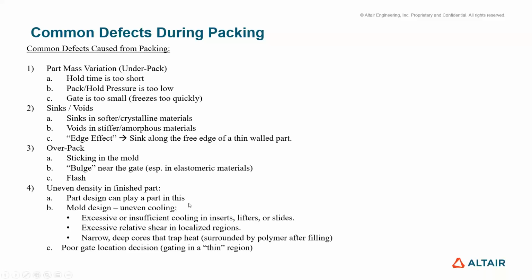If you're having dimensional problems, that's a problem with the build of the mold. If you try to process it out, you will lead yourself into other problems. And whatever you get from processing in packing, you will lose it over time because of the viscoelastic nature and the creep properties of polymers. It's a losing battle in the long run. If it doesn't come out as scrap, it will come out in warranty. Warranty costs you more than scrap because it also hits your reputation.